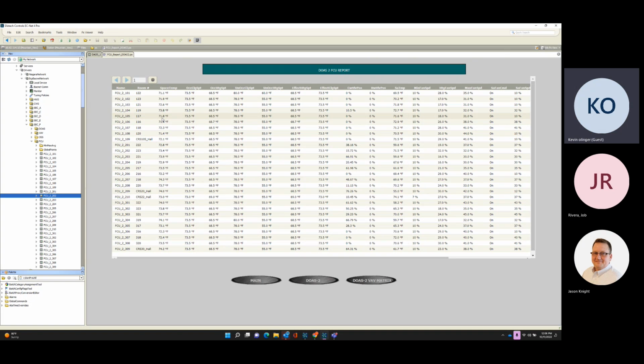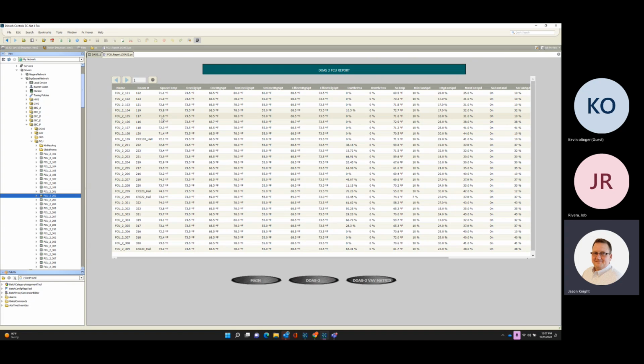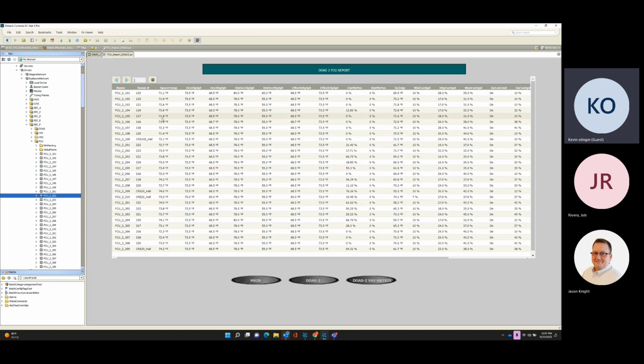Okay. And how many fan coils need to be calling for cooling or heating for the chiller or the boiler to fire off? For the chiller boiler, I was told by the engineer to do 2. If 2 or more are greater than 10% on their chilled or hot water valve. So the minimum fan coil is 2. What would be the minimum chiller or boiler demand? 2 fan coils or 2 air handlers.